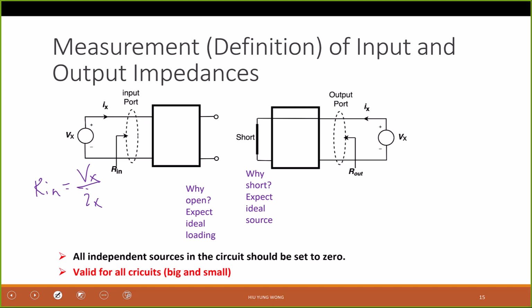However, it also depends on what load this circuit has. Maybe this circuit is driving another stage. Then in that case, you will get different results. So when we use the ideal case, we say that in the case that I_out equals 0, which means it has no loading, it has the input impedance equal to infinity.